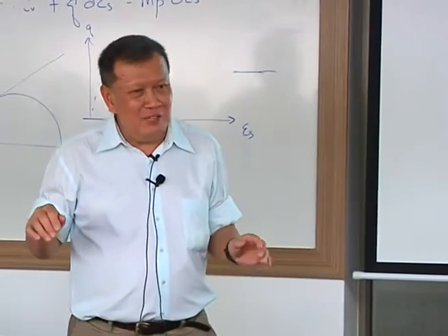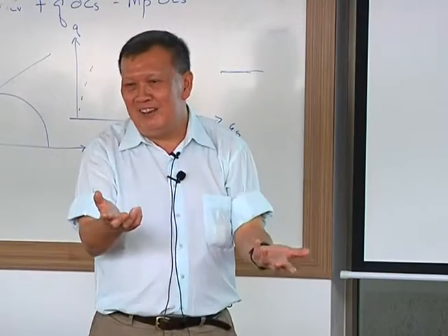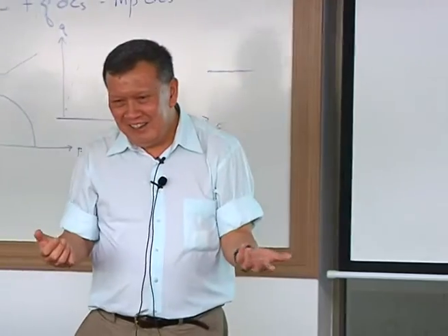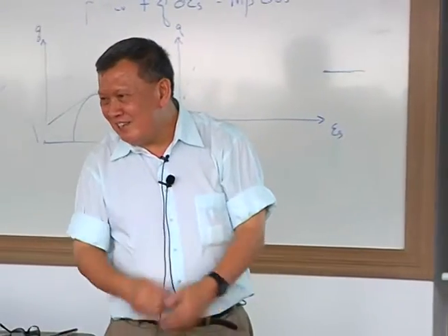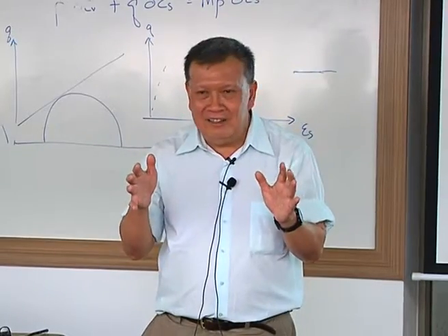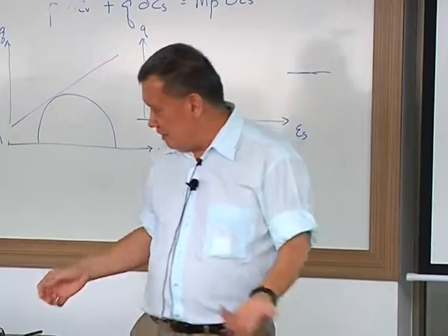And to the best of his ability, when he does one like that, and then he does the next guy, this guy is going to lose preload. And so that's how we end up with 30% preload. It's a matter of construction sequence. There's nothing devious about it. It's just human nature, they just do one by one. And that was exactly what happened.